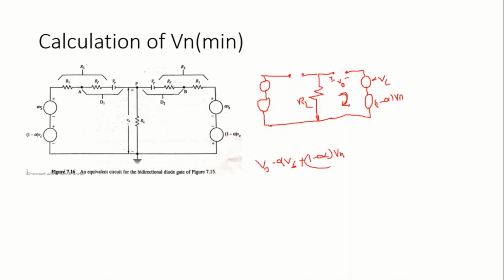By considering the worst case for both diodes to stay reverse biased, the worst case is that some diode may enter into forward bias. So for the diode not to enter into forward bias, this Vd should be 0. This is the verge, the edge of the value at which the diode may enter into the conduction, forward bias state.